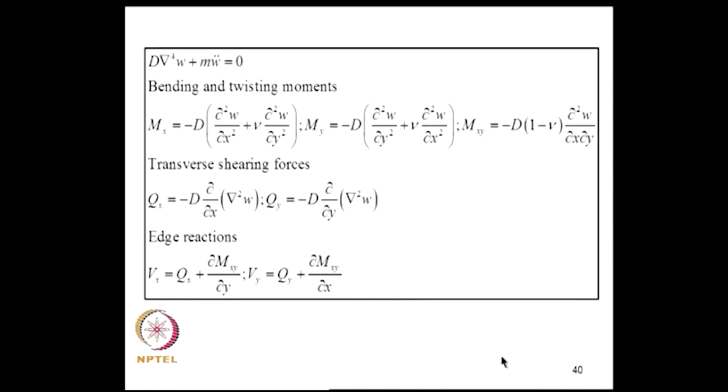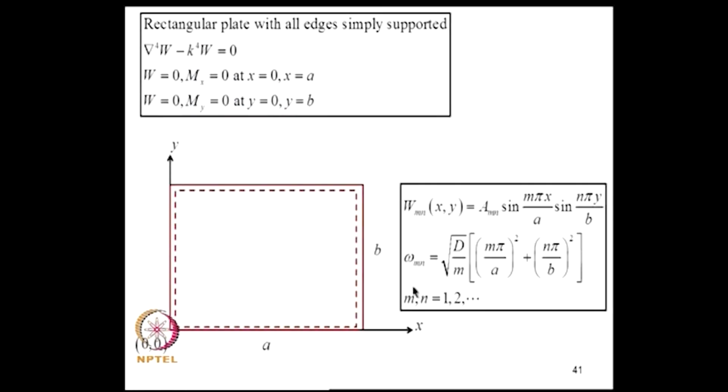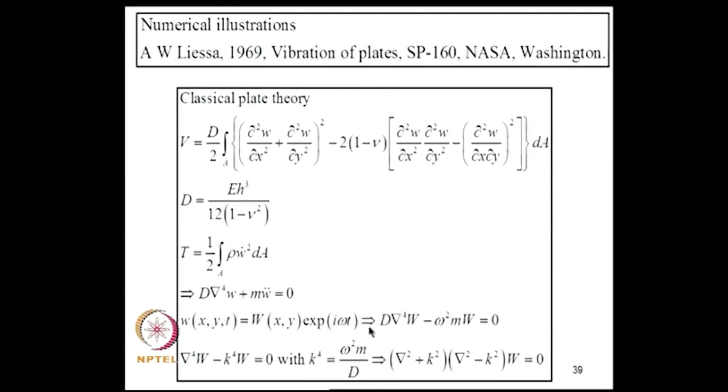Now, there are a few other details here. This is a governing equation and these are the stress resultants in terms of the displacement field. This is the bending moments Mx, My, Mxy, twisting moment, transverse shearing forces and edge reactions. These are results from classical plate theory. I will not be getting into the details of these equations, but I am stating them for the sake of completeness. Now, let us return to the problem, that is the free vibration problem.